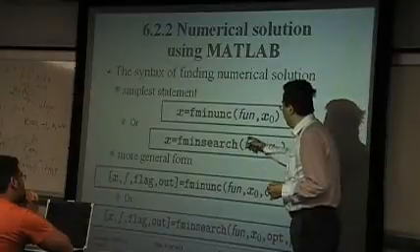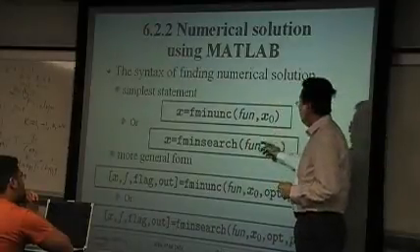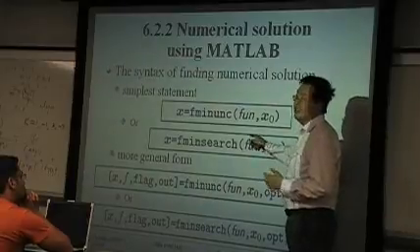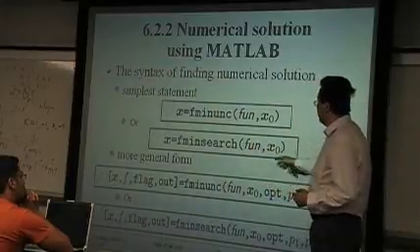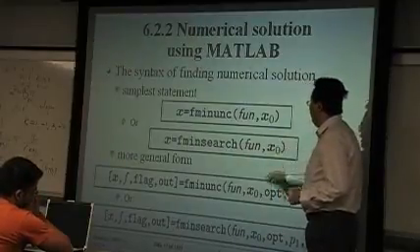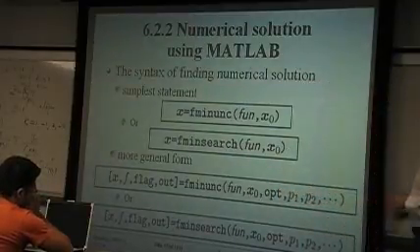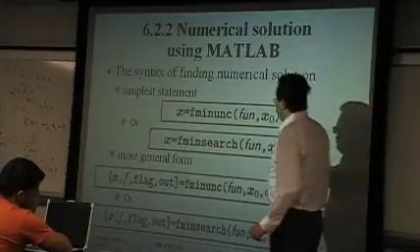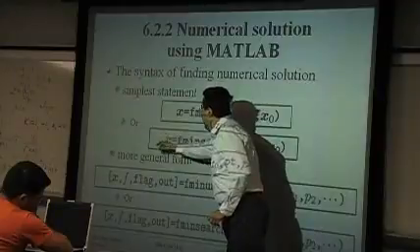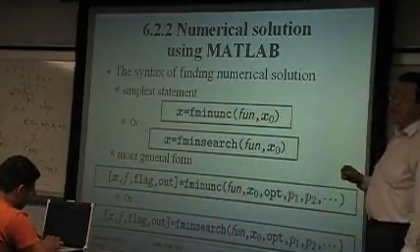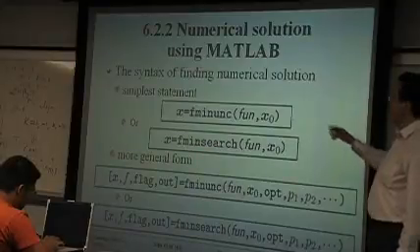And again, this function can be described by an .m file or an anonymous function. It is similar to the case in equation solutions. And also, we have to specify an initial search point. I shall explain that one later on. By calling this function, we can find x, which minimizes the original function.